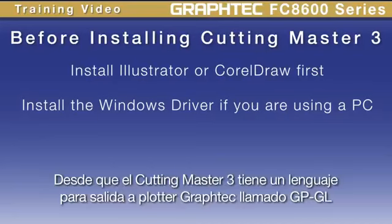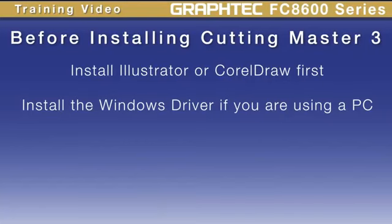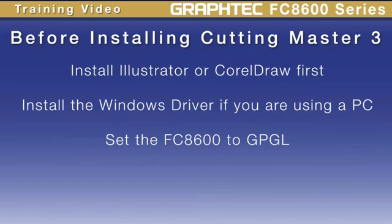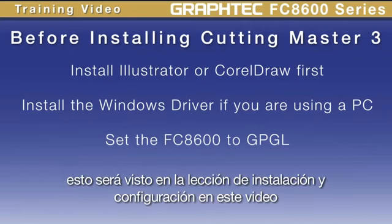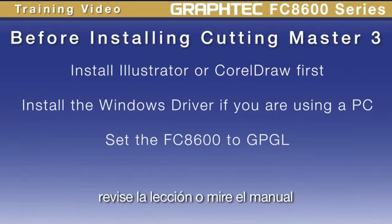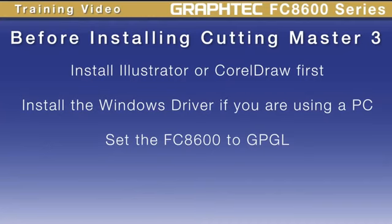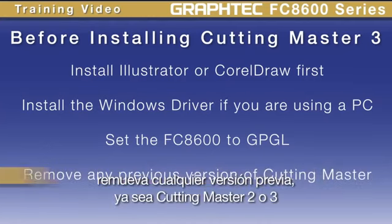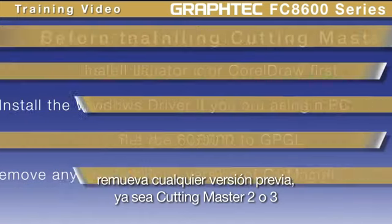Since Cutting Master 3 outputs to GraphTech's cutter language, known as GPGL, the cutter will need to be set to GPGL mode. This was covered in the installation and setup lesson of this video. If you're not sure how to do this, review that lesson or look in your manual. Finally, prior to installing Cutting Master 3, remove any previous versions of Cutting Master 2 or Cutting Master 3.